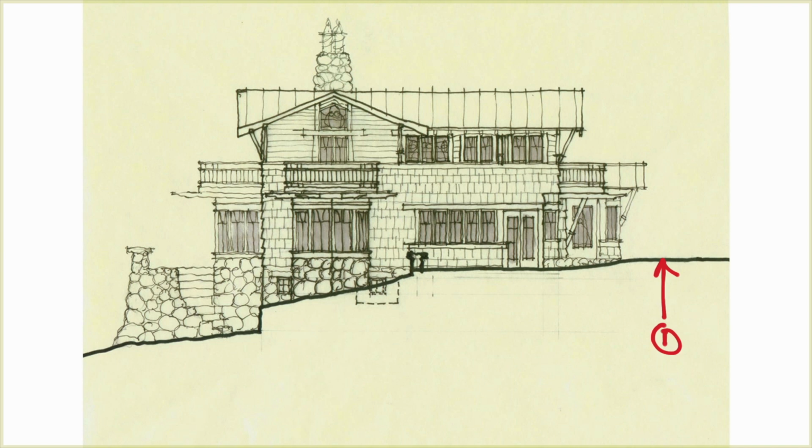As we go down from there, what's the next thickest line on this drawing? It's probably the thing that is closest to us, or sometimes it's the outline of the building itself. And this is a stylistic question. Sometimes people do a dark outline around the building so we see the whole perimeter to make it stand out from the background. Sometimes the next thickest line is going to be what's popping toward us. So I would argue that the next thickest line is either right there, because this little piece is popping out toward us. It's like a little bay window. Or potentially it's that piece, which has a match right over here on this side.